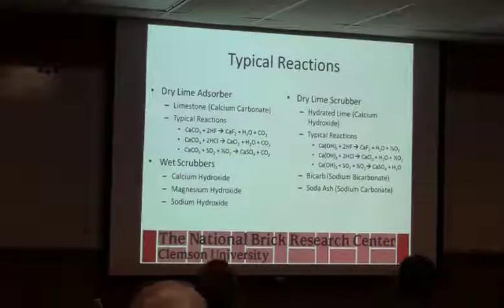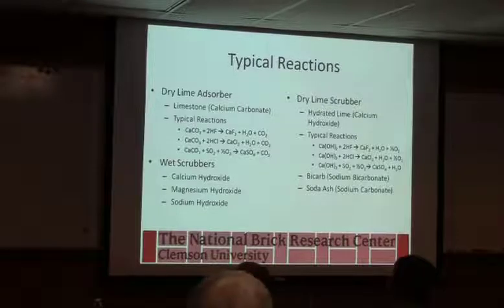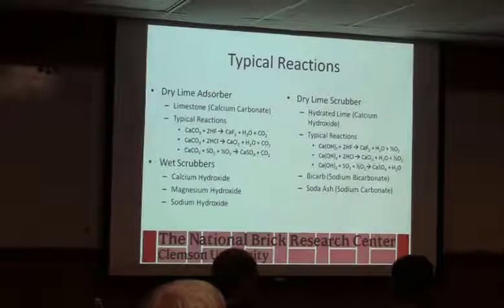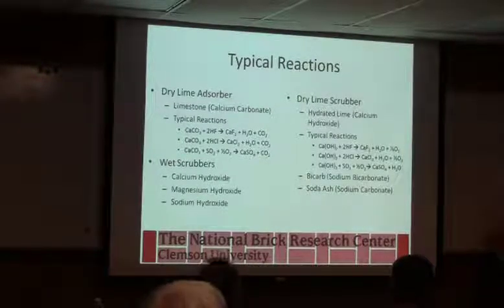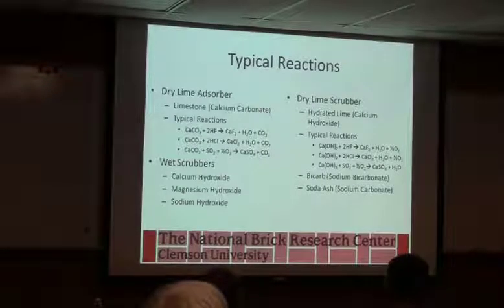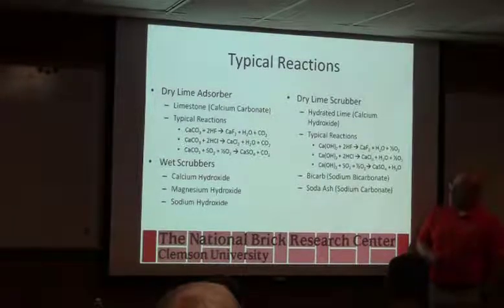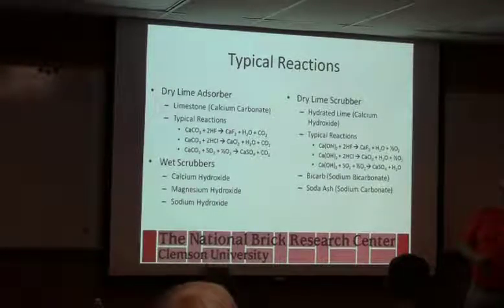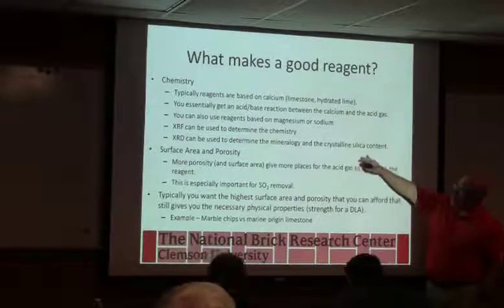On our rotary kilns, we do a wet scrub. What do you do with the water? Well, we have a big containment pond that we have to check the pH constantly in, and add sodium hydroxide, we call it caustic soda, to keep it neutral. Okay, that works. I didn't know you had to do that on your calciners. Yeah, all our calciners have a wet system.